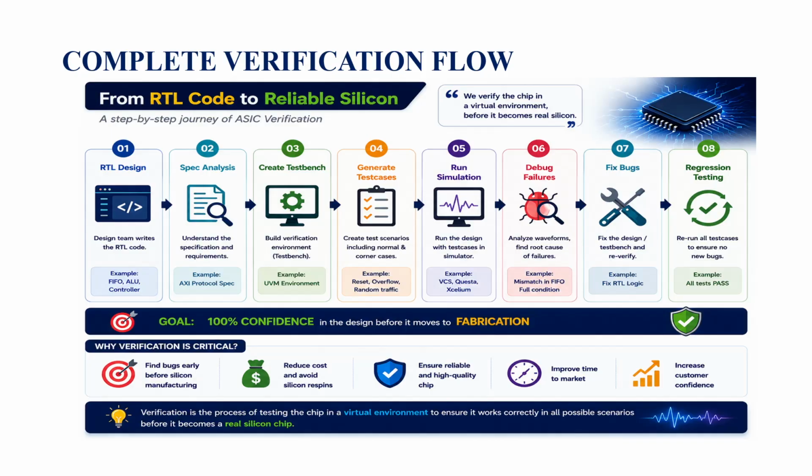And also we have to write how we are going to do that, whether we are going to verify with the help of assertion, coverage or scoreboard, that we have to mention. We will have one idea on how we can perform that. After that, whether it is pass or fail, and why it is passed or failed. That is a brief overview of the test plan.